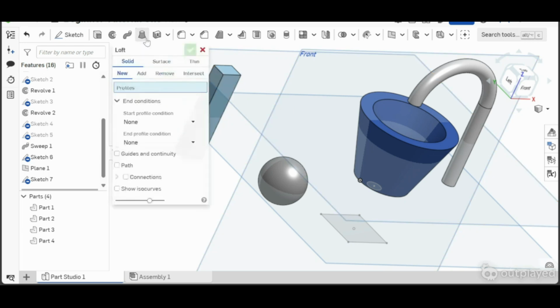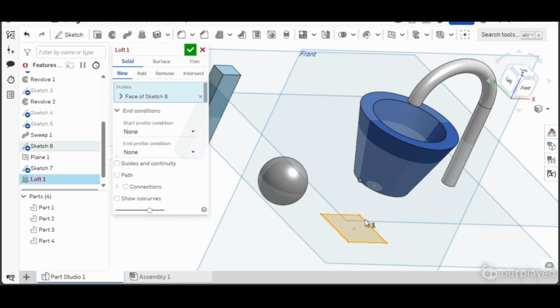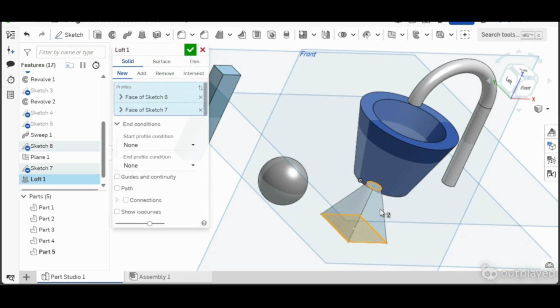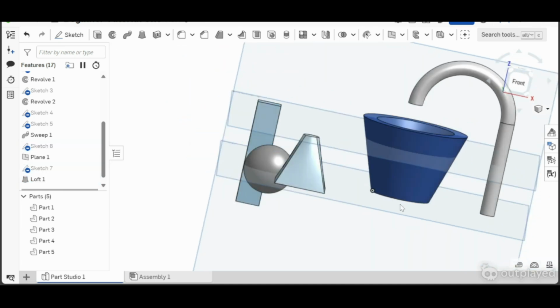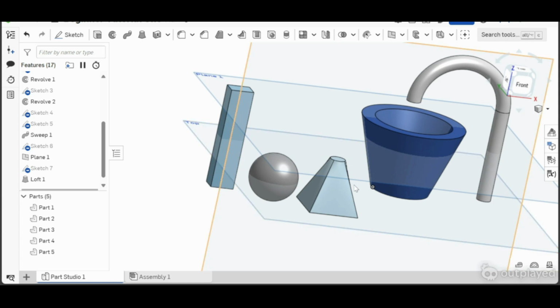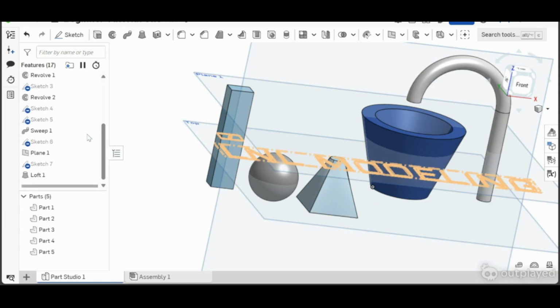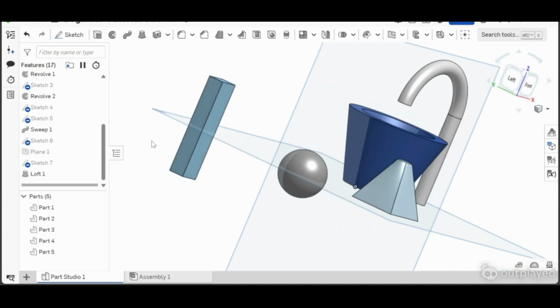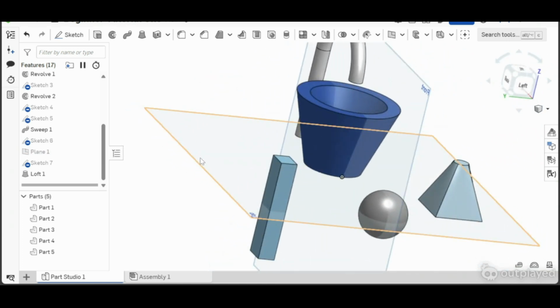But it's a lot easier with Loft. If you go here, you click square, and then you click the circle that we made, and we have the same shape I wanted. Now, if you've noticed, you can actually see that there, besides new and add, there is a little bit more. There is a remove tool, and I'm going to show you how that works.